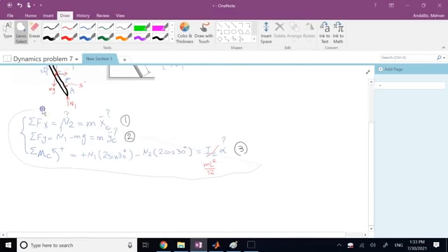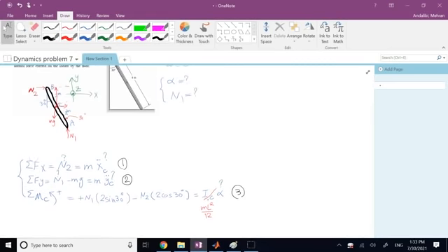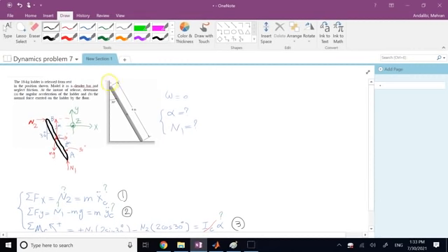And as I always say in my class, whenever kinetics is a dead end, go back to kinematics. Go back, see what constraints you have, right? What kinematic constraints can give you. So here you have point B to only move vertically on the wall and point A to only move horizontally on the ground. Those we have not used so far, so we have to get some equation from them. How? Since here is the acceleration of point C, and that's what we need, there might be a chance that I can find them, or I can relate them to this alpha through my kinematics equations.